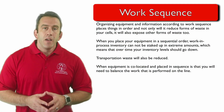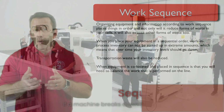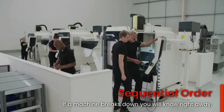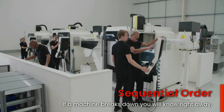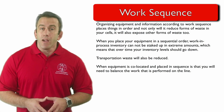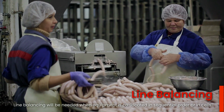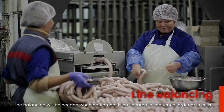With this in mind, it will also expose many opportunities for you. For example, if a machine breaks down, you will know right away. When a machine goes idle, you will see the issue right away, and you can get it fixed as soon as possible. Another opportunity that will become obvious when equipment is co-located and placed in sequence is that you will need to balance the work that is performed on the line. This is referred to as line balancing.